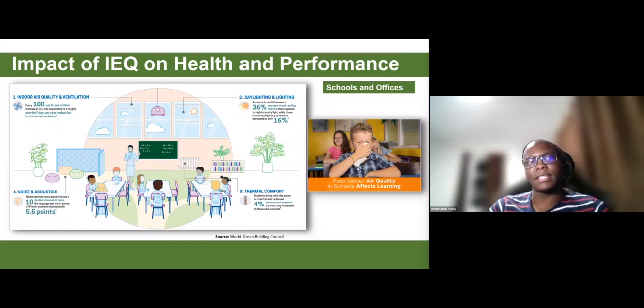The phenomenon is that when you have many people inside an enclosed space, after a while, the CO2 level rises because we breathe out CO2. And high CO2 levels have been associated with a reduction in cognitive performance because it reduces your attention span. Good daylighting has been shown to improve the overall attitude, satisfaction, and well-being of building occupants. It can suppress melatonin production, which improves alertness.